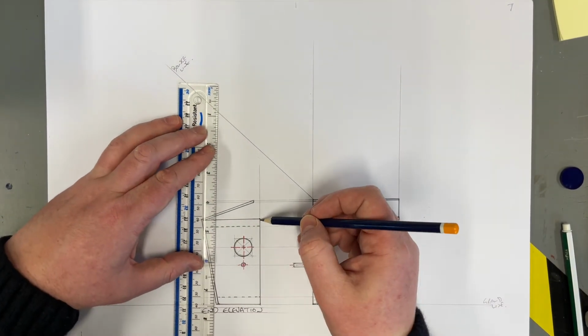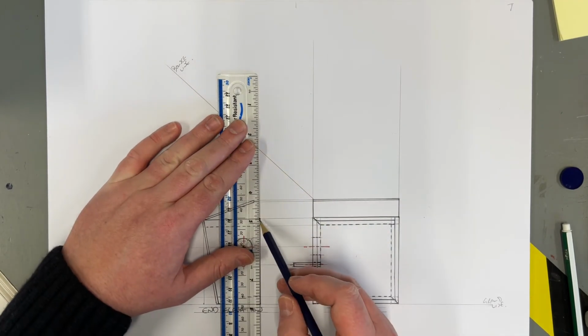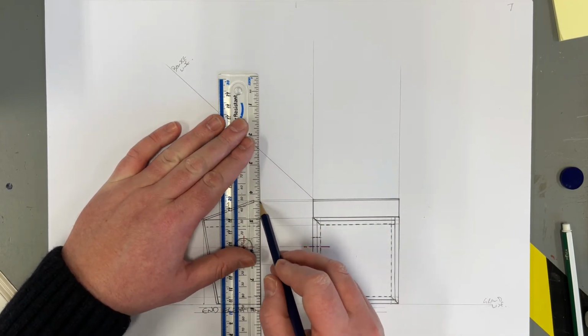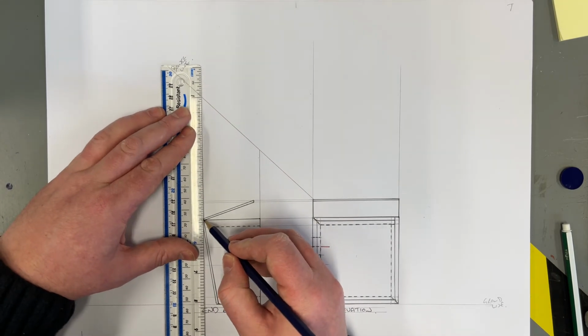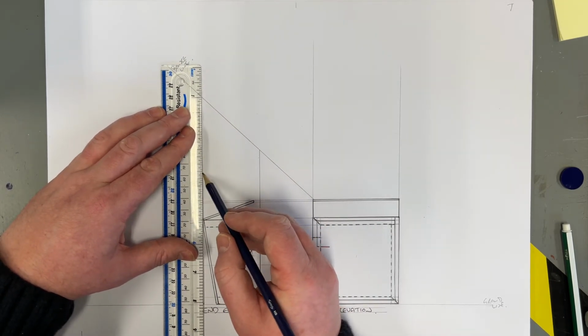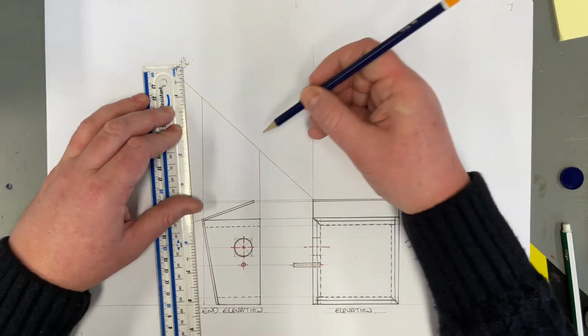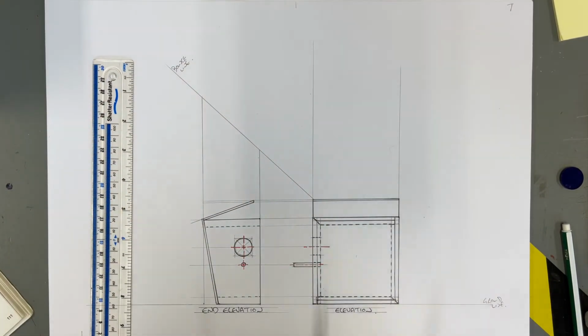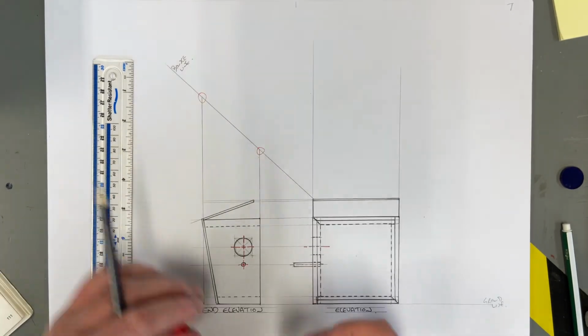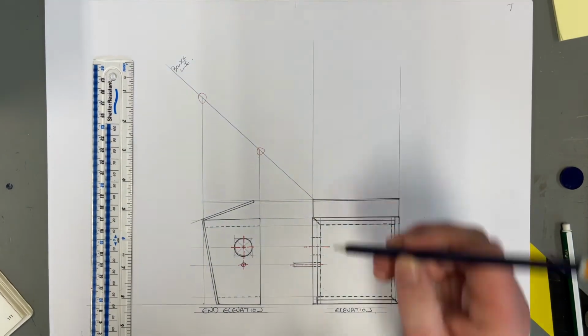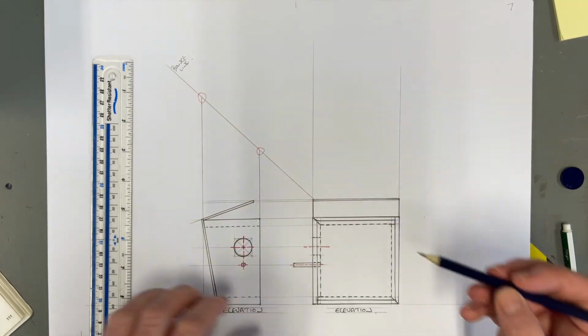And I'm going to take all of my breadths and project those up for the wooden box. So that's that one to that one. I'll just connect them up vertically to the bounce line, and that gives us a little intersection. You wouldn't do this, I'm just circling it in red so that you understand. So that would give us a little intersection that happens here and here.